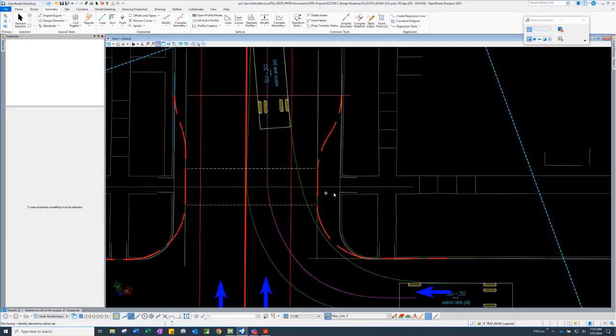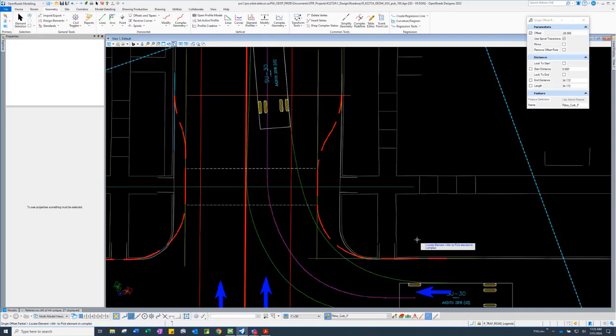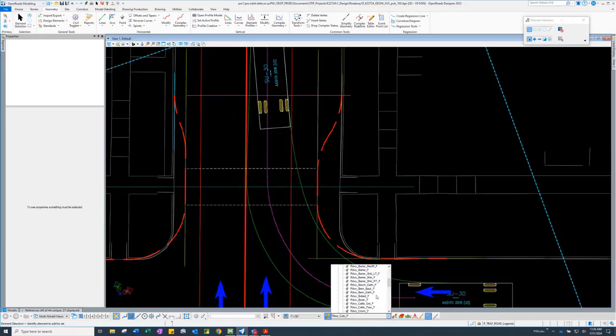Okay, so from here, and even after it's complexed, if you change one of those control lines, it will move with it. That's right. So from here, I would go to the next stage, which is I want to know where the ramp opening is. So I'm going to do a single partial offset. Now I like to draw construction lines. Not everybody likes to do this because I can get more rules stacked on top of each other. So I don't want to overwhelm people, but I do construction lines for all the ramps first and then draw over the top of them, kind of like the driveway.